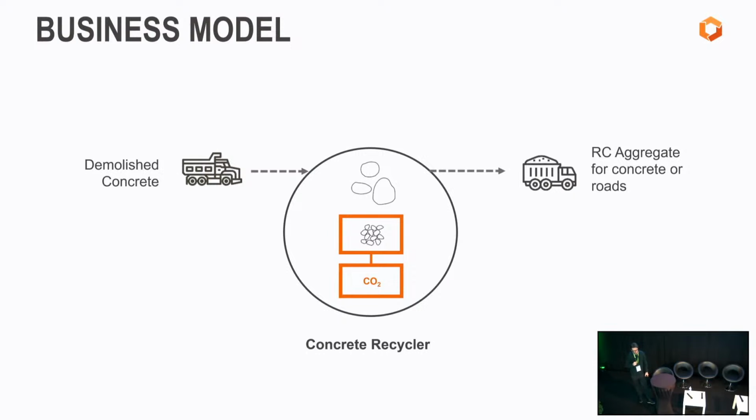Now, where we come into place is that we produce machines which can be used at the concrete recycling plant, where the recycled concrete can be placed into the installation, and we inject biogenic CO2 over the course of 2 hours up to 12 hours. And we close the bunker for the time of the injection. What happens is that the gravel, or the recycled concrete aggregate, during this time takes the CO2 and permanently binds it back into limestone again.